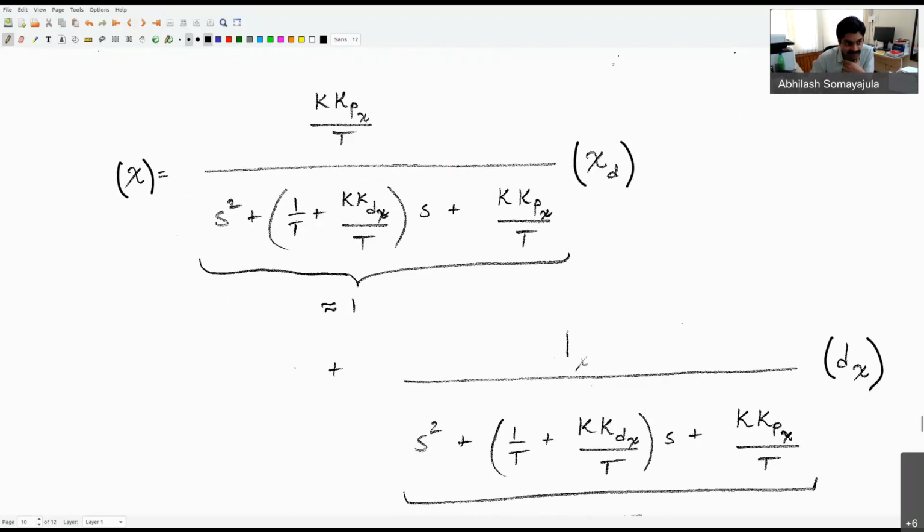Okay, so the second order system is now going to try to stabilize the system. So over the range of frequencies of interest to me, I at least want to see that this transfer function is maintaining a value close to 1 over the range of frequencies of interest to me. And then beyond that, I want it to go off to 0. No issues there. Okay, but the downside is when I choose that system to have a value 1 relatively good, it is also allowing the disturbance to have all those values to be passed down, because the denominator is the same for both these cases, right?